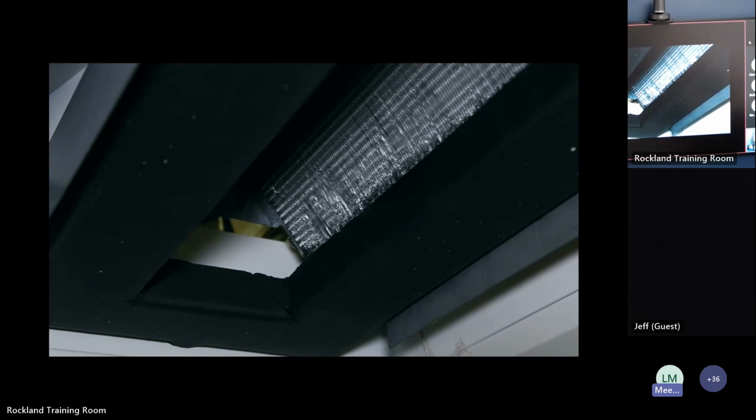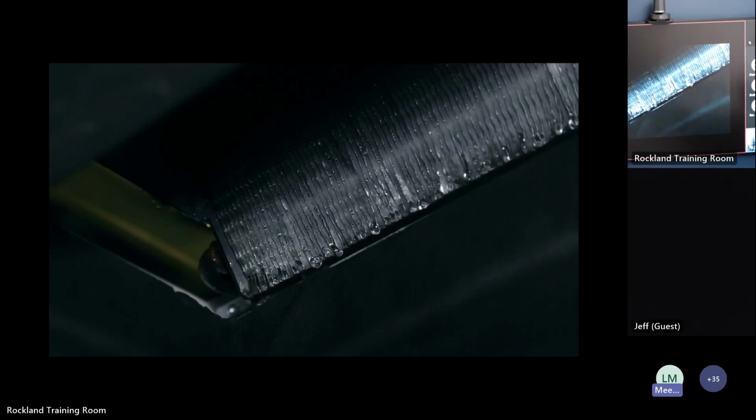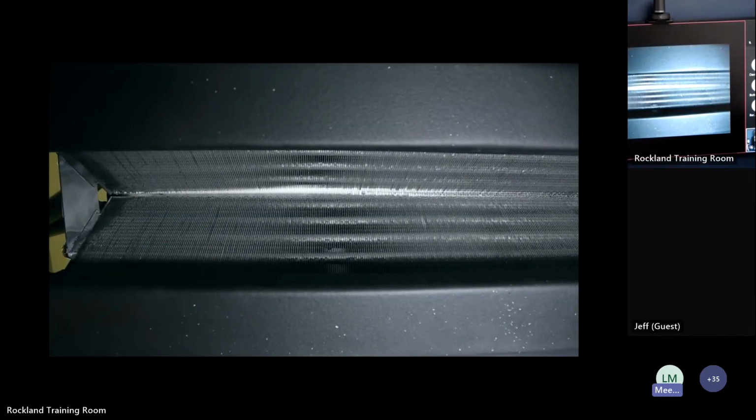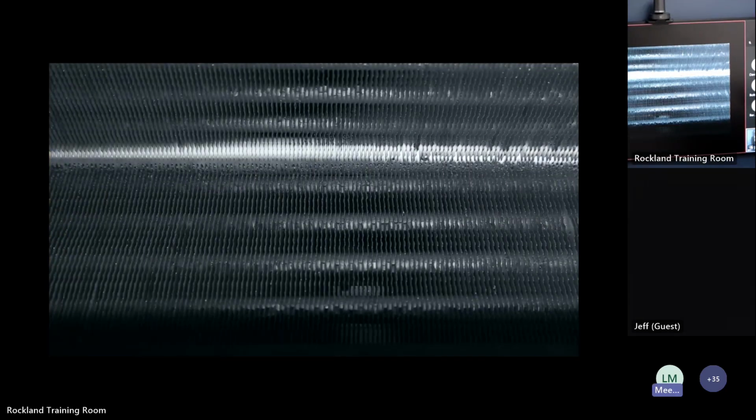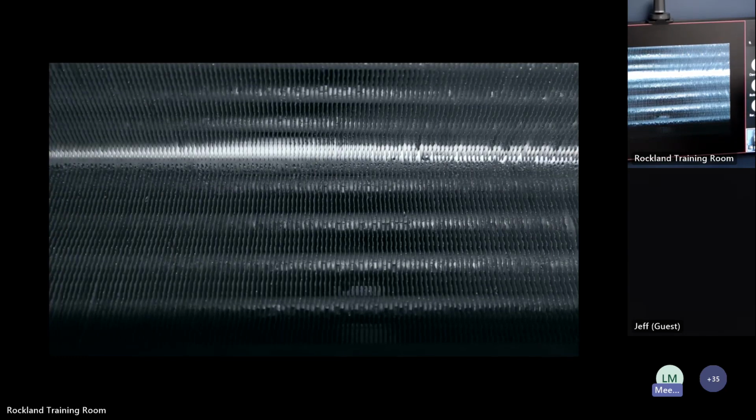This is a video taken in our lab with the face brought down, and essentially we pumped that lab room to get it as humid as we possibly could and ran subcooled water to the chilled beam. So you can see that because we're inducing room air through that coil, it's very low velocity. We don't have 500 feet per minute, not even 300 feet per minute running across those coils. So it's really low velocity and it doesn't have any of that condensation detach from the coil. So that just drips down to the edges on either side here into that drain pan that you saw.